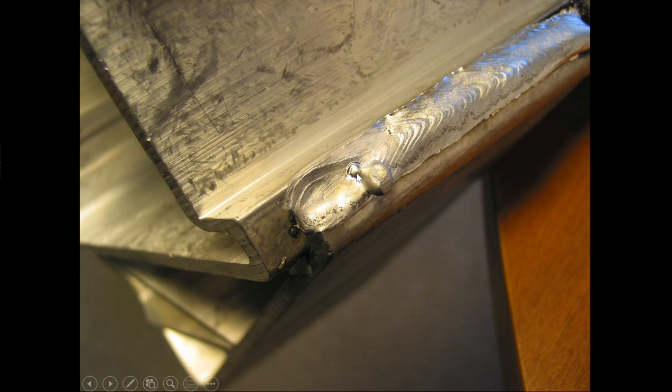So something happened though at the crater condition where we were trying to execute a crater fill, and you can see the contact tip was dying because it ended up spitting out a little bit of material here at the end. Now I just want to say that this is one, just because it's out on the outside edge, that I would fix. However, there is, by specification, I just want to note, nothing wrong with that crater, because it doesn't go into the base metal.